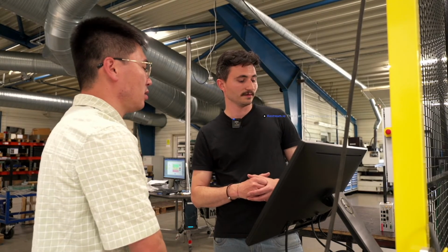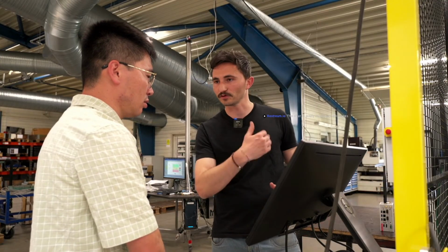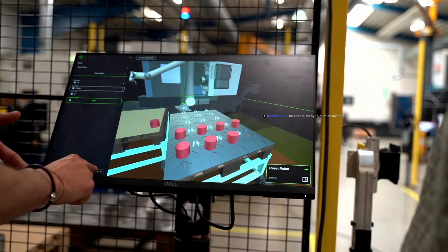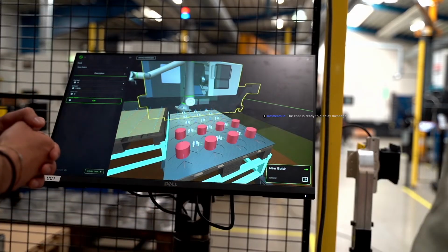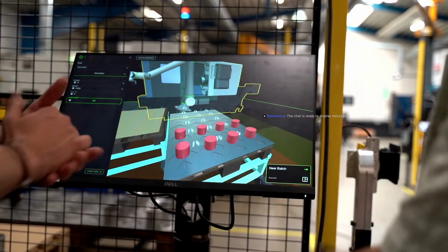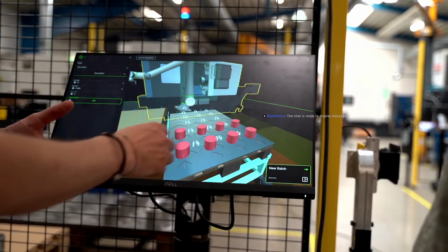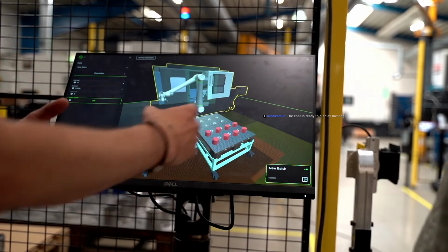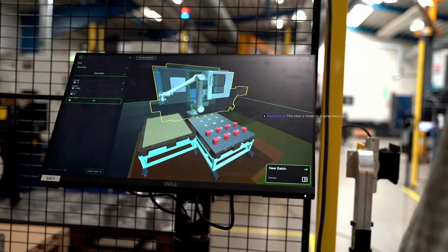Another parameter is the batch size, how many parts you want to produce. And finally, if you want to empty the drop-off. In this case, we have some garbage from previous operations that we want to clear out. So the operator just has to start the task, and it will run very quickly. Here, success. You see that a new batch of 8 parts has been created, and it matches what we prepared physically in the cell.